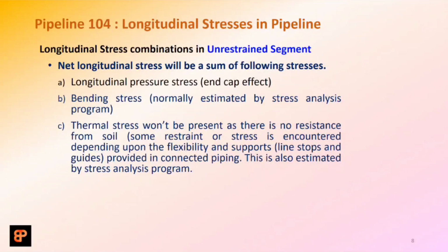So it's not going to happen in the unrestrained segment. So this will not see thermal stress. There will be some resistance from the piping, as I said, but it will be determined only by the stress analysis program when we do the combined modeling. So thermal stress won't be acting in this section.